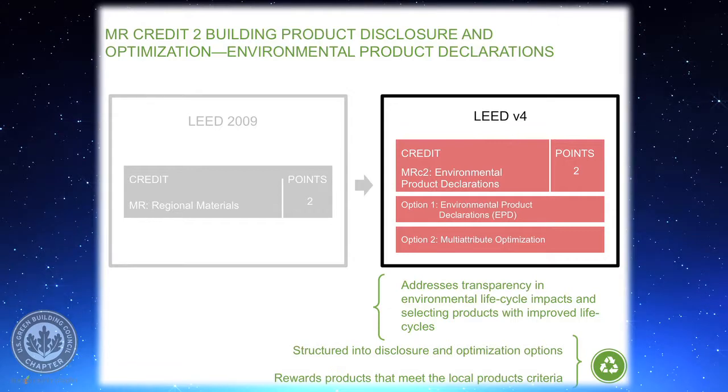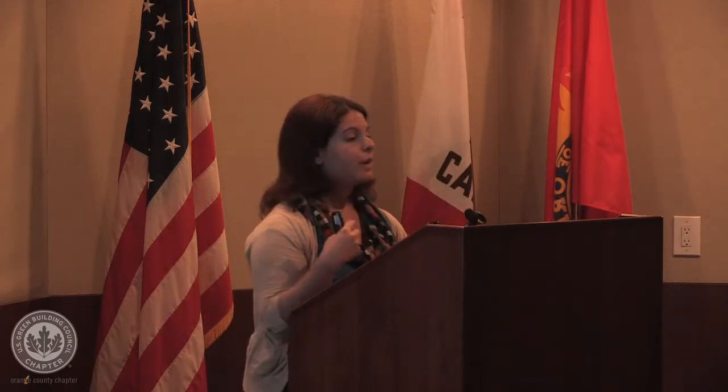And we chose 20 because in LEED 2009, in order to document, say, the recycled content credit, project teams typically document between 60 and 70 different products into the different materials calculators to meet those different thresholds. So 20 is based on a couple of different ways that we value EPDs, knowing that some projects may need more than 20, also recognizing that there are fewer EPDs in the market than products with recycled content, and also we want to encourage project teams to try to reach that threshold.